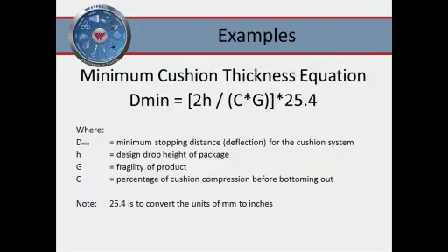Okay. Now that we've gone through three pointers: one, determining product fragility, secondly, improving the product, and thirdly, cushion materials, let's give you some formulas and calculations that you can take home with you. This is mainly a pen and paper exercise, and let's just say that this is the only data you have. With this being the only data you have, you could still calculate your cube, your dimensional weight, and how many units per pallet you could fit per packaging configuration with this formula here.